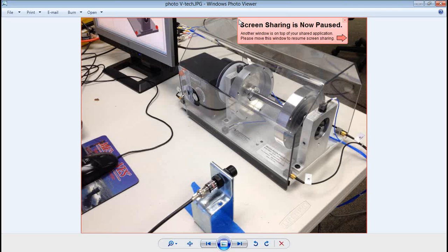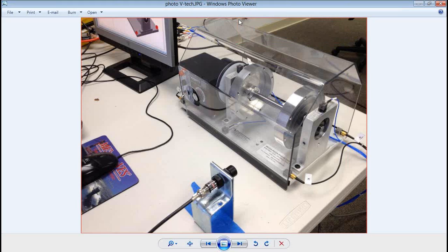Okay. So, little technical issue, but this is what's called a Vtec Rotor. We purchased this from a company, Vtec, down in Atlanta, Georgia. This is very handy for looking at ODS data on a rotating piece of equipment. Here you can see a tachometer, and there's a piece of tape on this one rotor, so we can actually measure the speed of the rotating part of this machine.